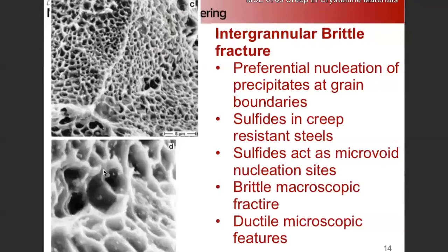This is one of the mechanisms for these precipitate-free zones. The other is free vacancy quenching, because the grain boundaries are a good source of vacancies. So if you have nucleation reactions that depend on vacancies for nucleation points, there's not a lot of vacancies near the grain boundary because they've all been sucked into the sink. But precipitates growing at the grain boundary.